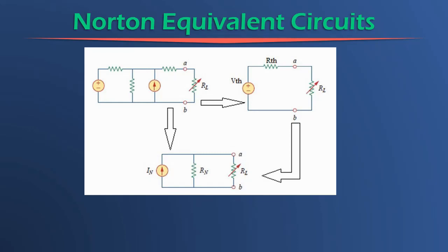So as previously discussed with Thévenin equivalent circuits, the objective of this section is to obtain a much more simplified representation of an otherwise complicated or complex looking circuit. Previously we looked at this complex circuit and indicated that it can be simplified to a single voltage source VTH, a resistance RTH, which is the equivalent resistance, and the original load resistor connected at the load terminals AB.